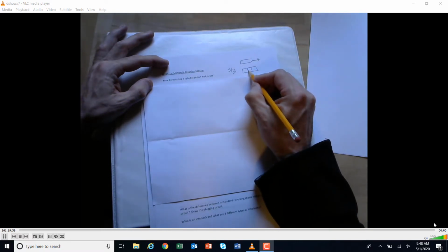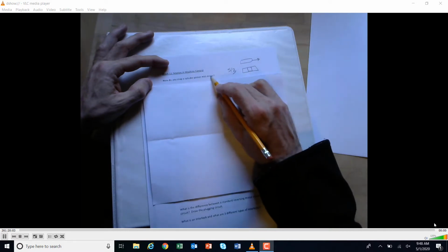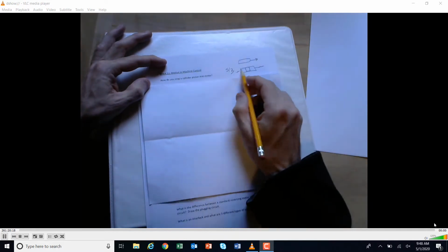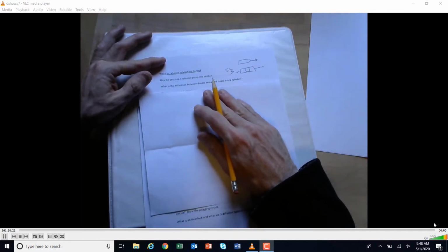And so with this center state, while it was extending, you would have to kill power, which the spring would return it to the center state, and it might be teed off, and then the cylinder would kind of stop mid-stroke, okay? So that's how you would have to do it. You'd have to use a 3-position valve and kill the power mid-stroke.